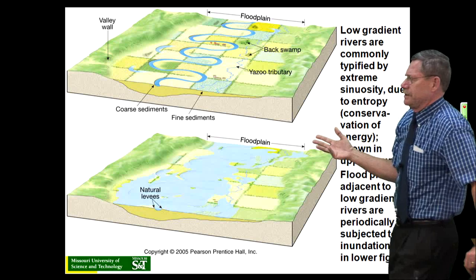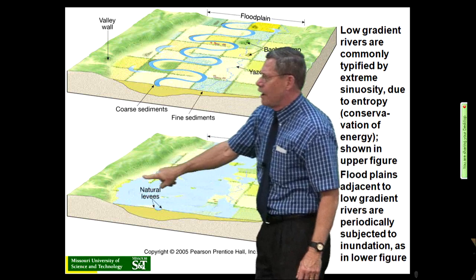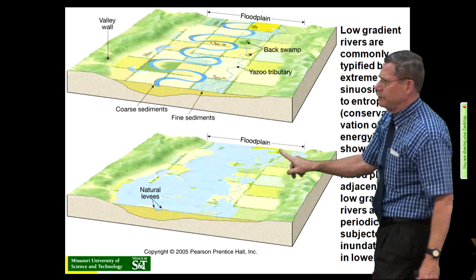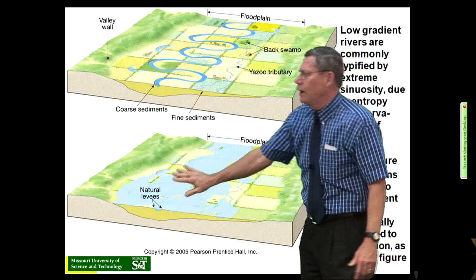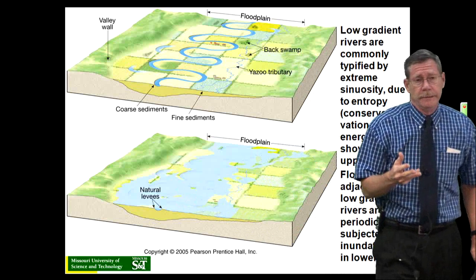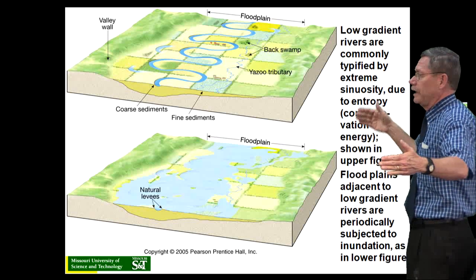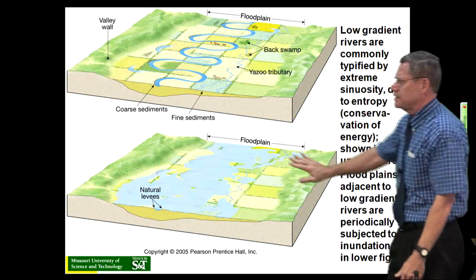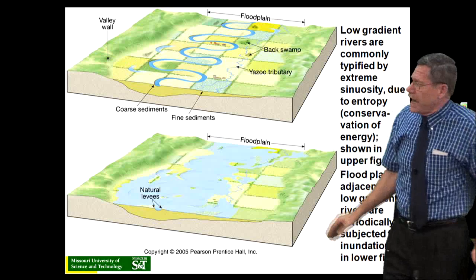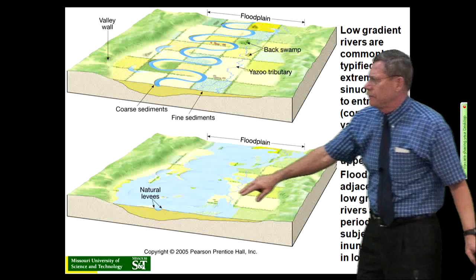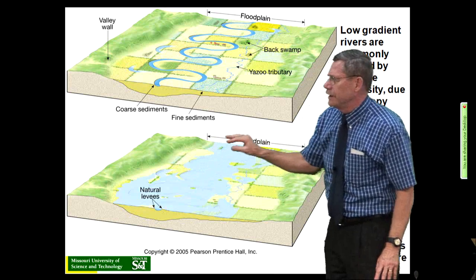But when this thing floods, and that's the high ground, the channel's the high ground, here's what happens. The whole darn floodplain becomes a swimming pool. Not part of it, not the right part, the whole thing goes underwater. And this is what happened along the lower Missouri River and middle Mississippi in the '93 floods. You just saw the whole entire floodplain, cliff to cliff, miles across, go underwater, and it was underwater the whole summer. So that's the problem you're battling with when you try to dike these things off and protect these developments that have been put in here and there selectively.